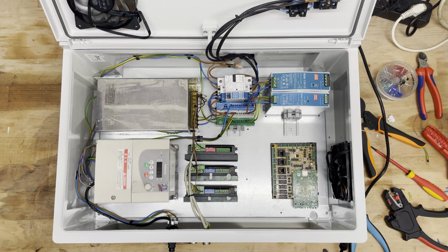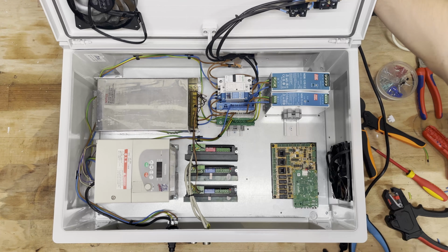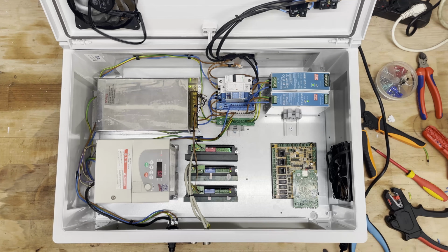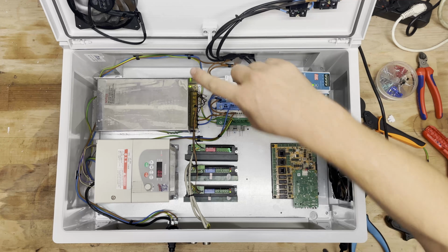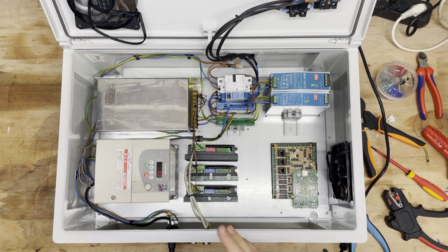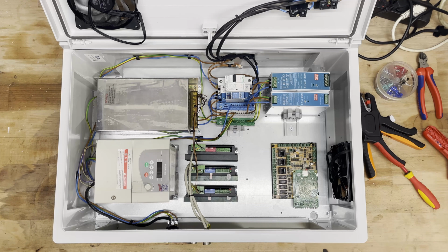Next then is to test that everything turns on and behaves as it should. Okay, we have power to 12 volt, 24 volt, the motor driver as well as the VFD. Looks like everything works, so I will turn it back off and then wait a couple minutes for everything to slowly discharge. The plan is to continue with the 24 volt and then finally do the 12 volt side, just going from highest voltage to lowest.